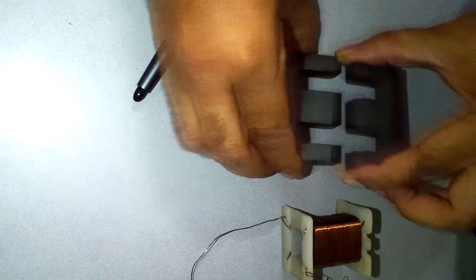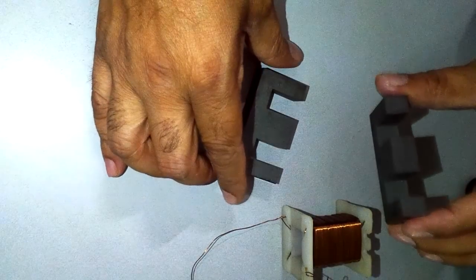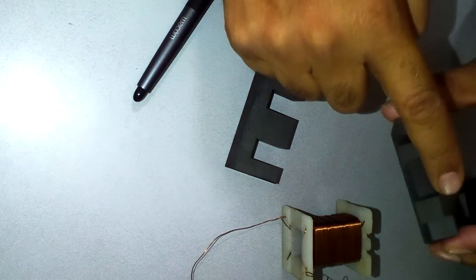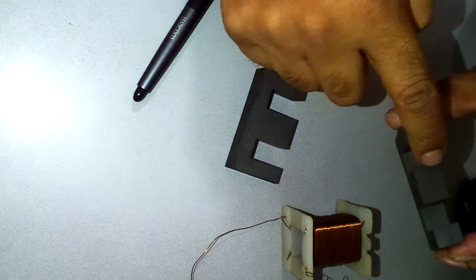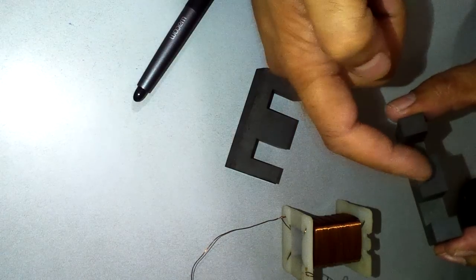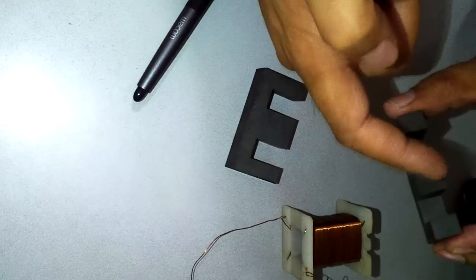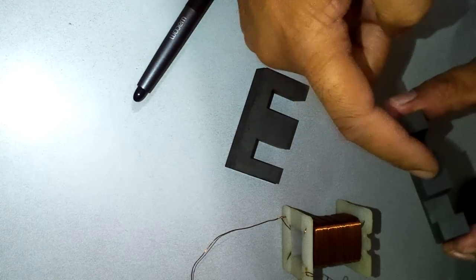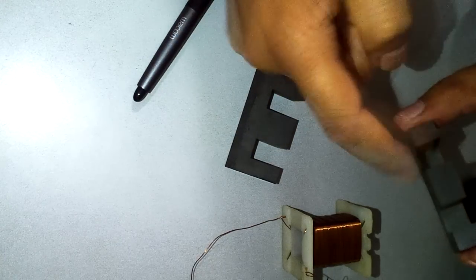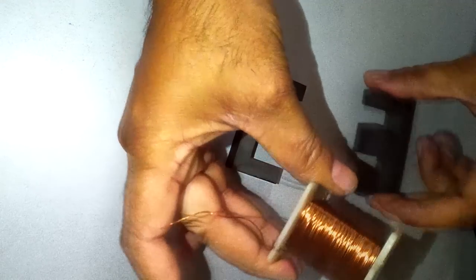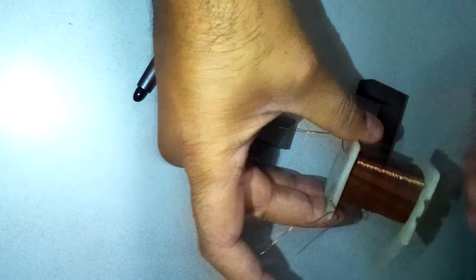And if I remove these two parts, and then if I show to you the facing part, this portion, what you see is the core cross section area. When you put the winding here and the flux flows in orthogonally to this core cross section, this is the core cross section area, and this then splits into two half core cross sections. So actually this is a bobbin, and on the bobbin the windings are wound.